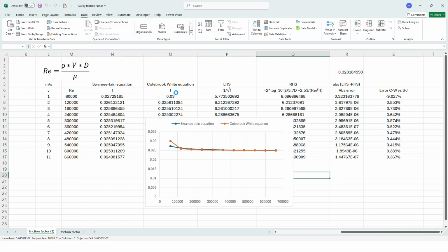Of course, it's not going to try every single value within that. It's going to use an evolutionary algorithm such that it gets to a solution quicker. When the function is smooth, it does not make sense to use this. The GRG method is much faster.